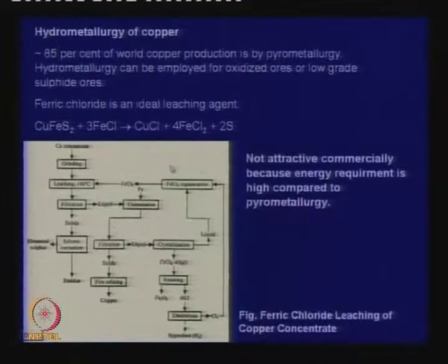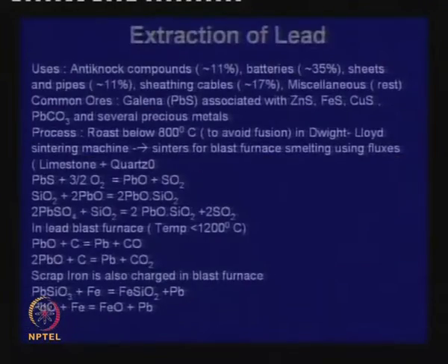We have talked about hydrometallurgy of copper, where the copper sulphide is roasted to copper oxide and taken into solution, and then once we have a solution, we go for electrolysis and electrorefining. There is also bacterial leaching. In the case of copper ores, some bacteria help take copper into solution, but that takes long time. It is ideally suited for low grade ores.